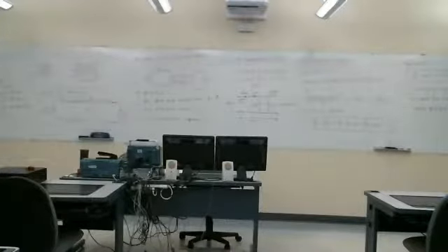It's a complex number, so from Euler's formula it has an amplitude and a phase angle, and the real part gives that amplitude times cosine of omega t plus the phase angle. But now our phasor is a function of distance. Previously in circuits it was just a complex constant. Now we're generalizing that a bit: it's a complex constant that's a function of distance down the line.